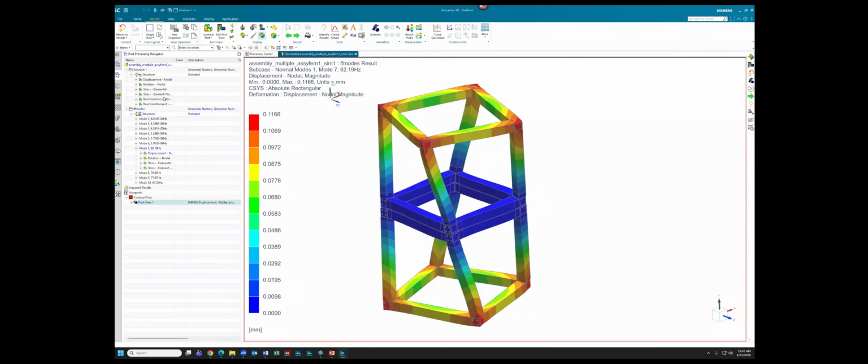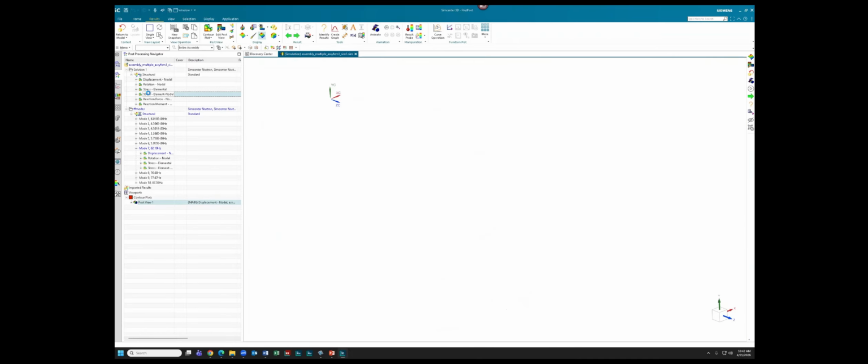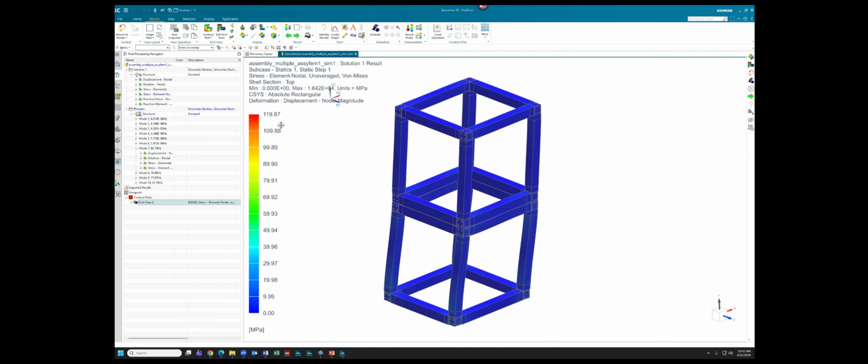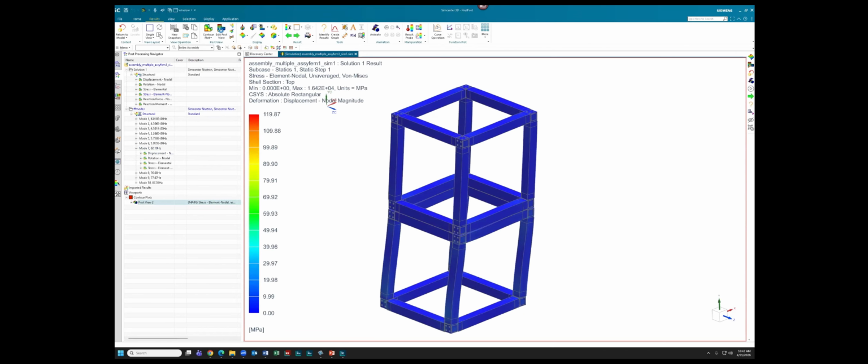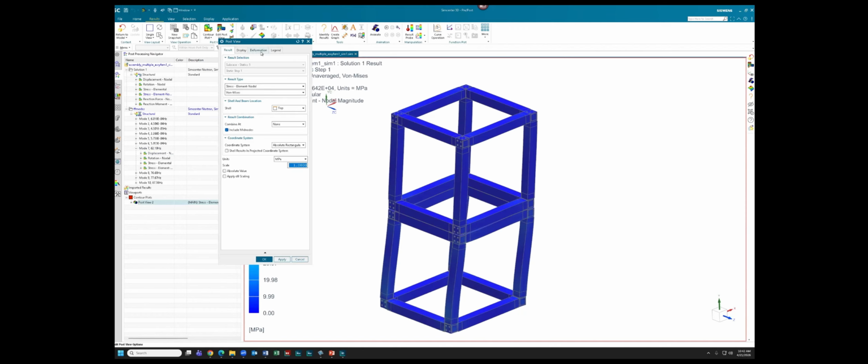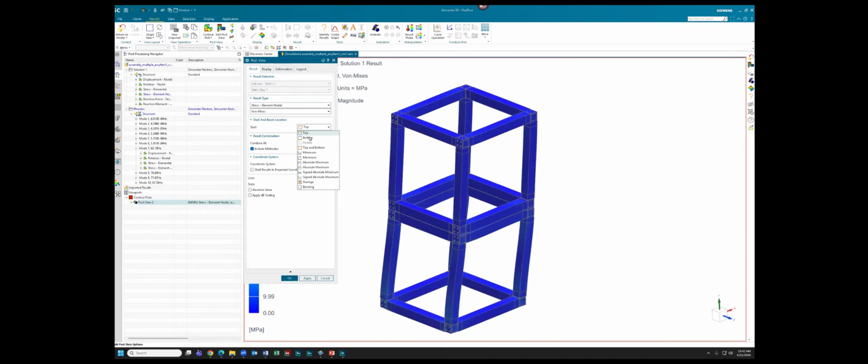Next, let's go ahead and look at that lateral G load model. Let's start with looking at some stress results. Then we're going to open our main post processor setting toggle here. We have tons of different options in here. For example, for shells, we can turn on where the shell stress is going to be documented. You can do top, bottom. In this case, we'll just do maximum. We can turn on things like nodal averaging.